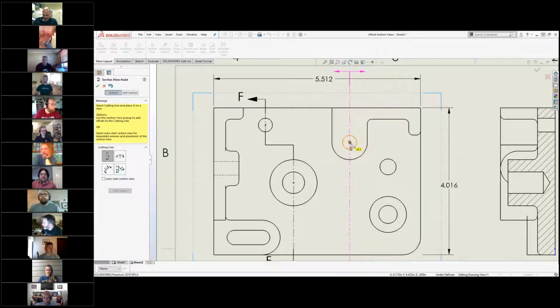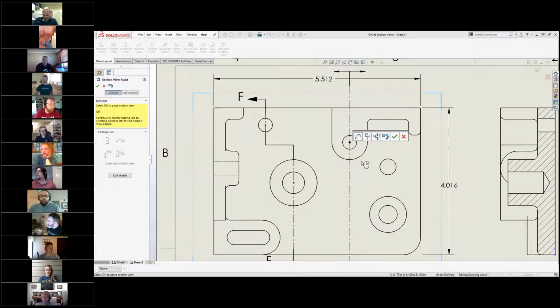So it's hitting. So if you click on that center point, is it actually creating a relationship? If you go and edit the sketch now, will you see a relationship there? Yeah, you'd have to delete that before you can remove it. Because you saw the yellow box. As long as that box is yellow, it adds the relationship.